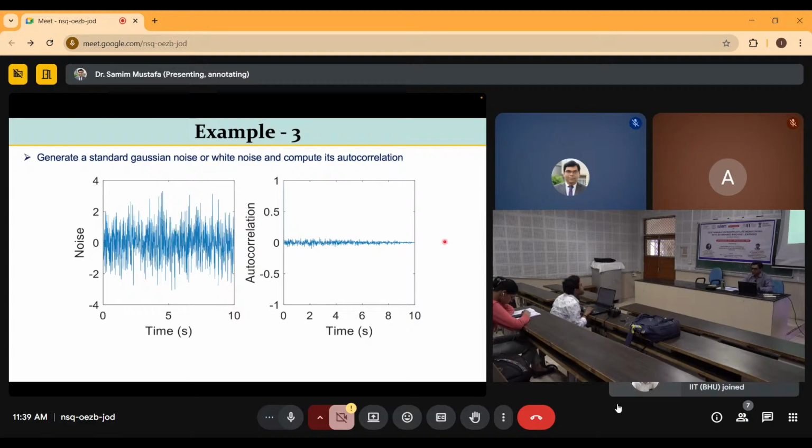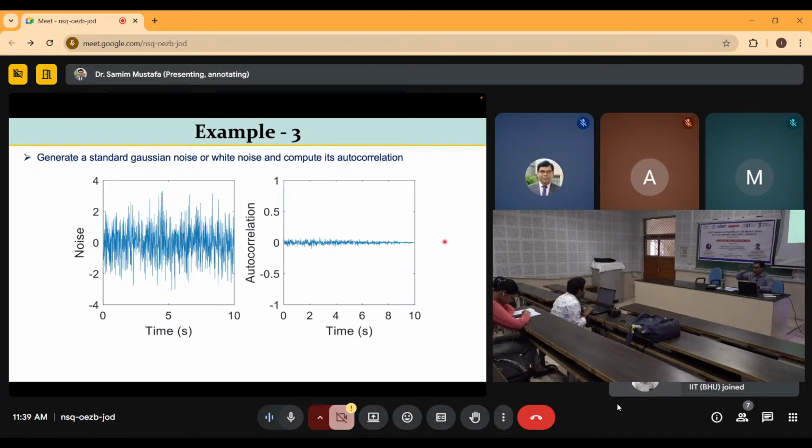So whatever noise, suppose you are doing filtering first, you are eliminating the noise from the main data, then you calculate the autocorrelation like this. You check whether the autocorrelation function is showing something. If there is some autocorrelation, then you cannot use the white noise modeling framework.